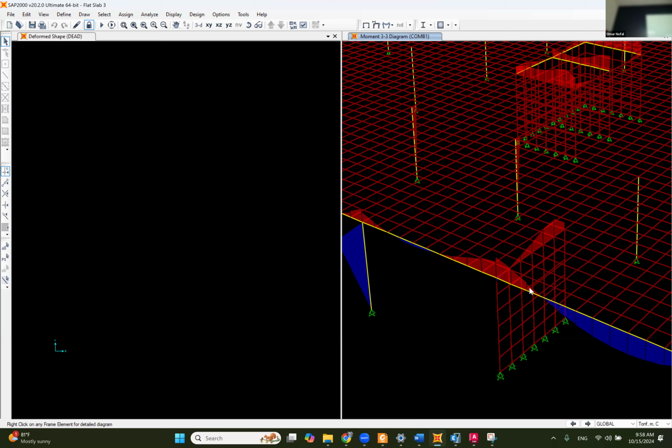If you sum the moment at the wall with the moment here, it's going to be equal to the value of the moment there. That's why the 2D model is more conservative. Why? Because you don't transfer any moment from the slab or the beams to the columns, because there is no inertia, no frame section that can absorb moment from the beam. It's just a hinge. That's why it's more conservative. The same thing here: the moment at the column is a little bit absorbed from here.